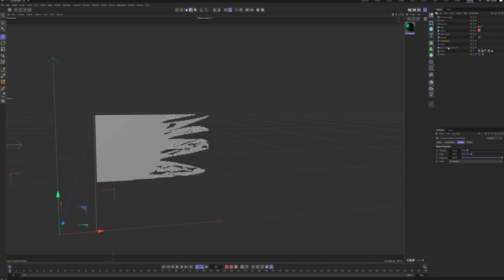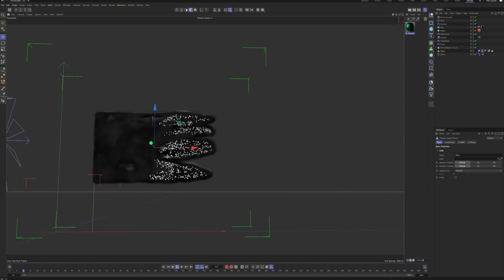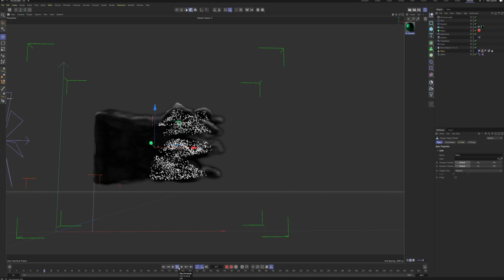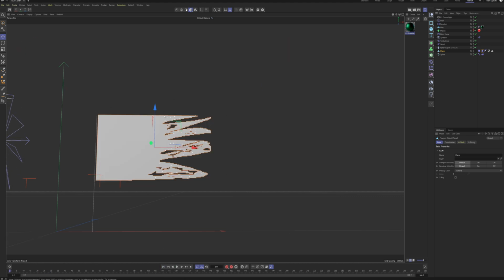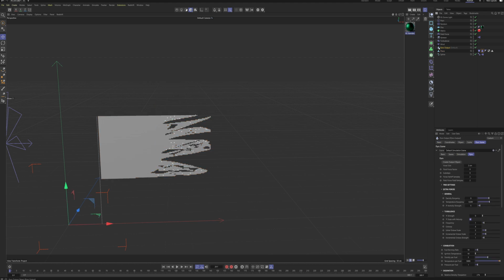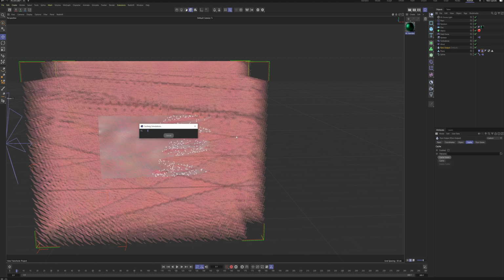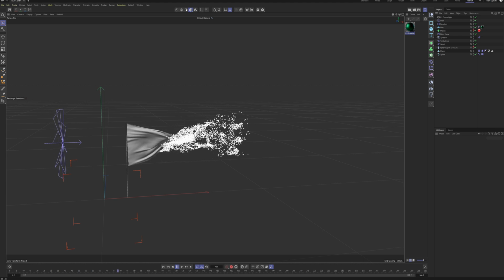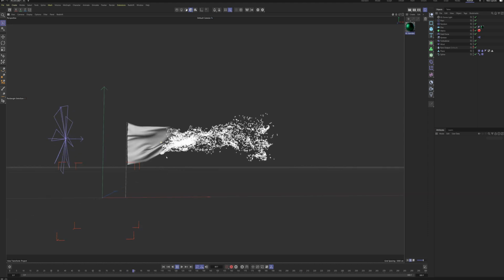And let's also go to our turbulence here, and let's set that to something more like 20. And let's set the scale to 30. Alright, so I actually think that should be okay for this. Okay, cool. So now let's just cache our pyro. Okay, so now it has cached the scene and it's looking pretty awesome, I think.